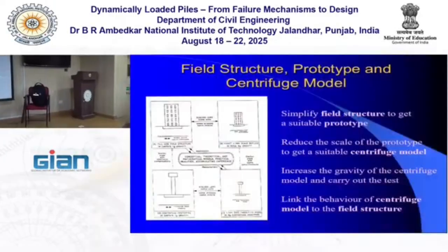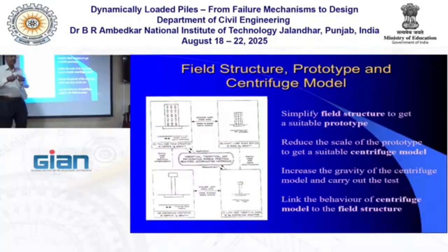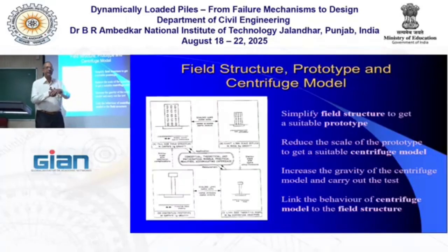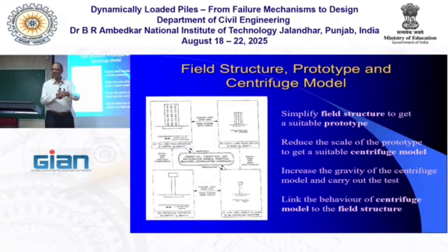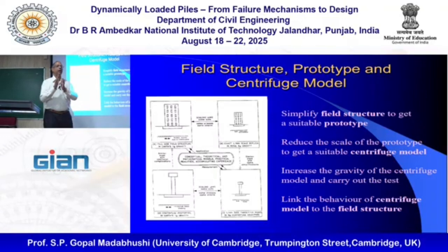Now in this sized model, I can't create windows, doors, the beam column joint stiffness correctly and so on. It'll be difficult. I can't actually scale all the structural components exactly right. So we don't do that. What we do is, you got to think here, what is it I'm trying to model? What I'm trying to model is the rocking of this. When the earthquake comes, this whole thing shakes and rocks. So I need this building to behave the same as that.